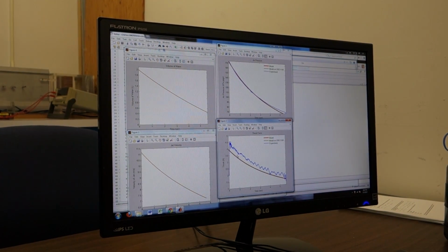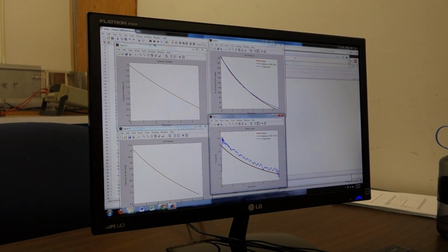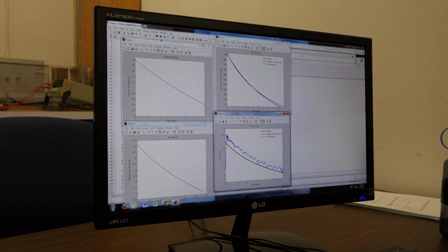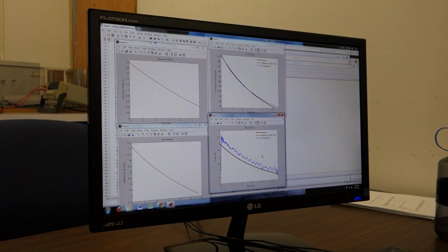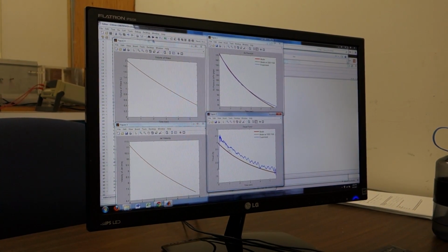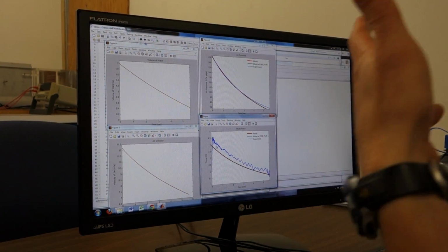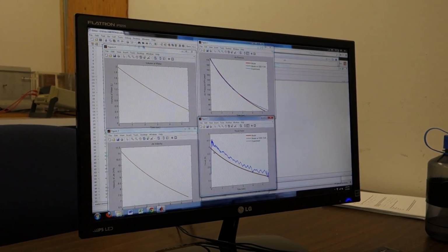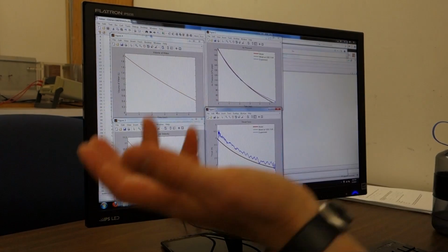This plot here is the thrust force, and we see it's more oscillatory, and this data is actually already filtered as it is, but it would be coming out of the computer even more wacky, and it also agrees fairly well. Looks like we're off by about 0.5 newtons. That's probably because the zero on the force gauge is not exactly the same every single experiment, because it's been deflected a little bit, just plastically yielded by other groups. So we see our plots agree pretty nicely.